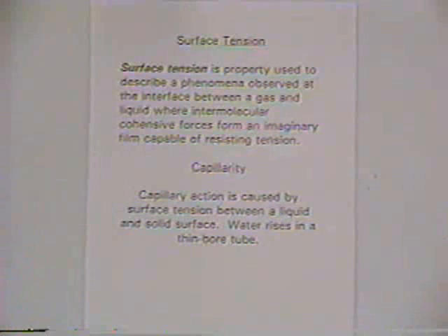And a related phenomenon is capillary action, and that's caused by the surface tension between a liquid and a solid surface. And you usually picture that as a thin bore tube. Water will rise up in the tube as the liquid adheres to the sides of the tube. Or in the earth, in geologic groundwater aquifer formations, where you've got sand and gravel and a water table, the water will rise up in the little porous media between the pores, between the sand and soil particles, due to capillary action.